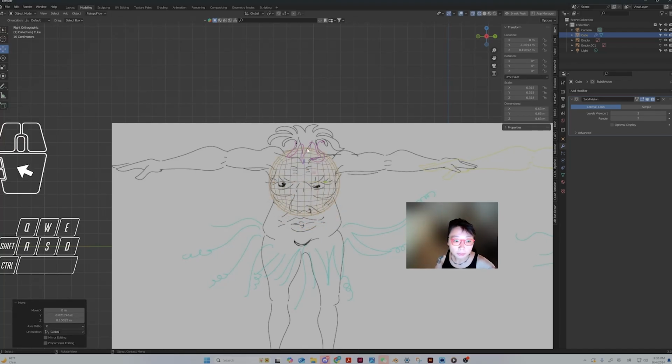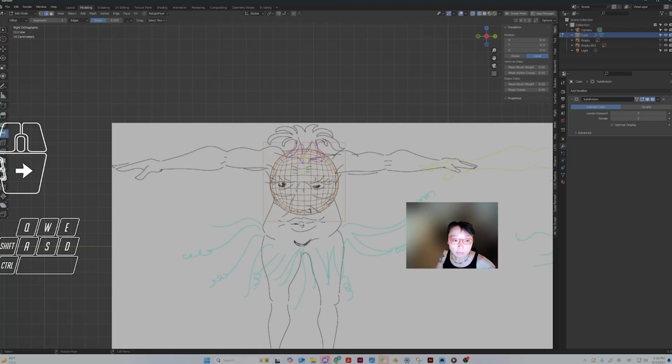We're going to try to place it, and break the torso down into 2 areas, right? Scale it down. And then, remember what I was talking to you before about edit mode? Hit tab to go into edit mode. Now you can see you can still edit the vertex, edge, and faces of the original cube geometry, and that will subsequently affect the subdivided surface underneath.